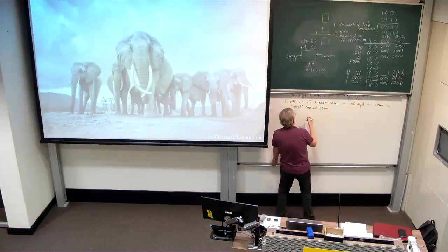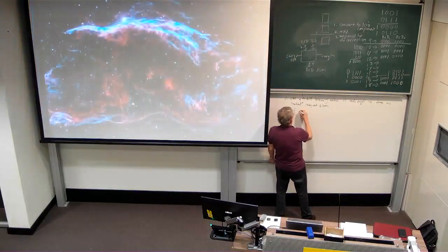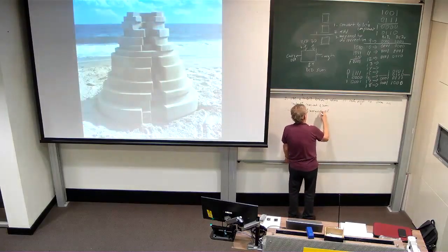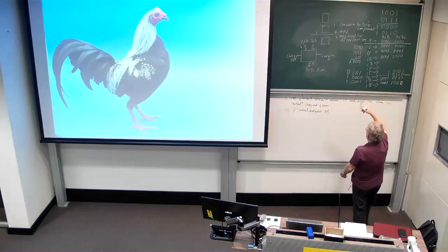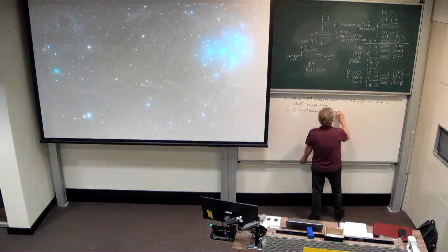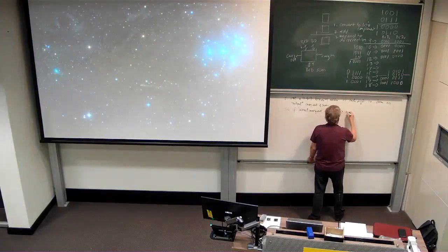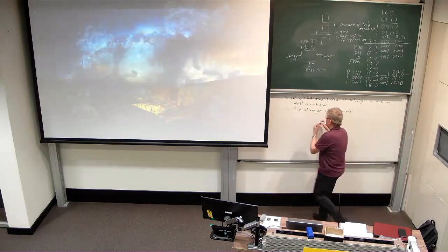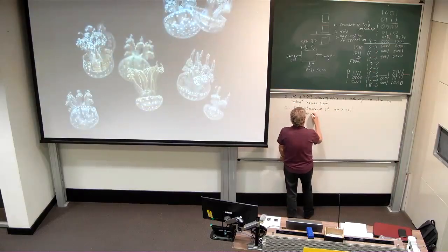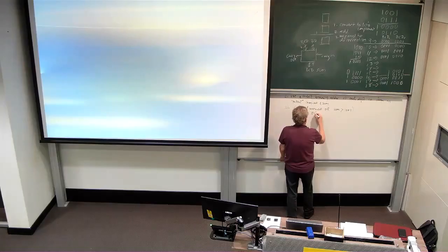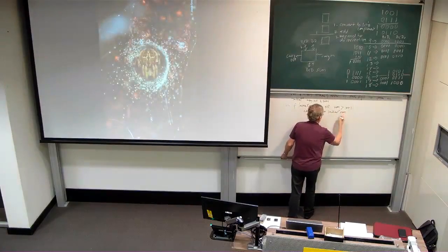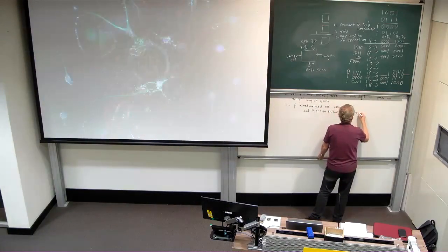If initial carry out or sum is greater than 9, then what we want to do is add 6 to the initial sum, to form the BCD sum.